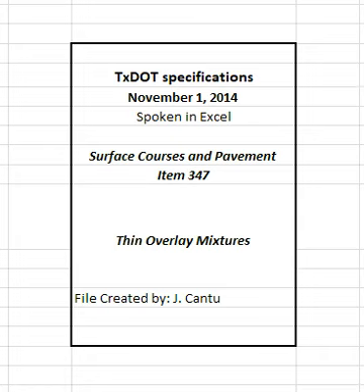4.3 Quality Control Plan, QCP. Develop and follow the QCP in detail. Obtain approval for changes to the QCP made during the project. The engineer may suspend operations if the contractor fails to comply with the QCP. Submit a written QCP before the mandatory pre-paving meeting. Receive approval of the QCP before beginning production. Include the following items in the QCP.